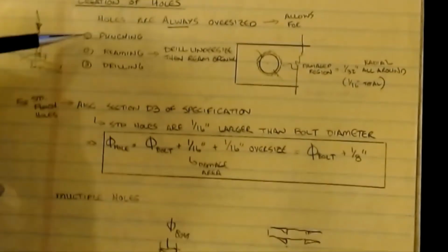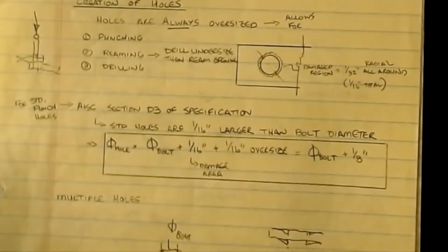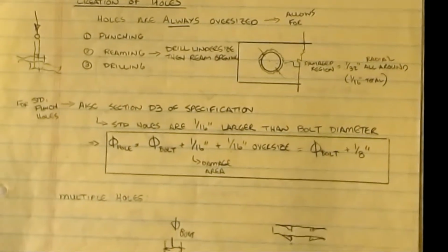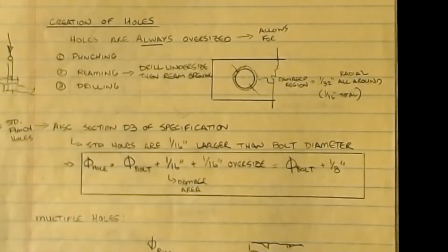But those are the 3 methods that we talk about when it comes to drilling or creating holes in plates for connections. In practice, we like to use bolts because they provide for a faster construction technique. All the holes are pre-made in a shop usually.